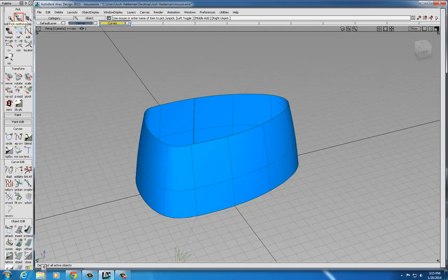Remember, this was a tool we looked at in class last week. It's called Pick Nothing, Pick Component. When you do that tool, it pops up these options over here. You need to always make sure you turn off everything except the Pick Curves option. They should all look like they're off. This one will look like it's depressed, like a different color or a different shade to indicate that it's selected. Draw a box around everything in your view, and it'll select anything that's a curve.